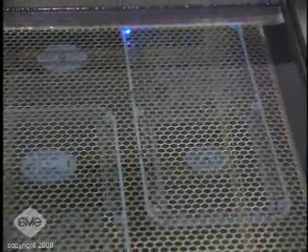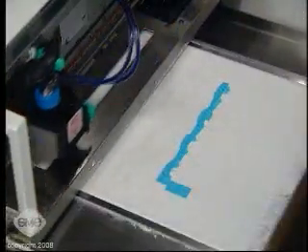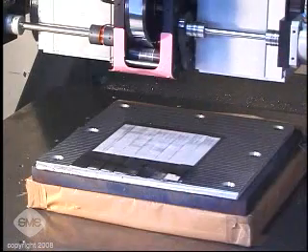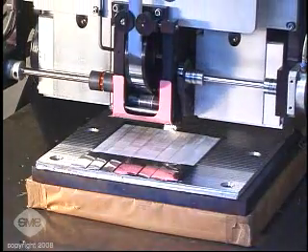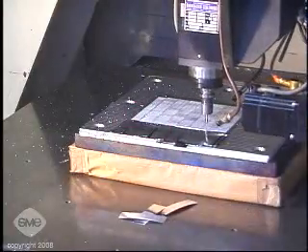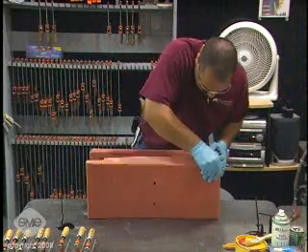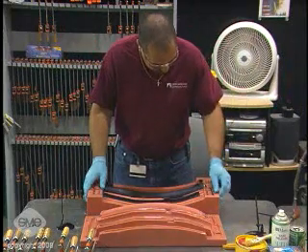Rapid prototyping is a general term encompassing a variety of systems used to create three-dimensional physical models directly from electronic data. These rapid prototyping systems primarily create models using a layer-by-layer or additive means of construction. More recently, though, systems using a combination of additive and subtractive layering and pattern-based rapid prototyping processes have developed.